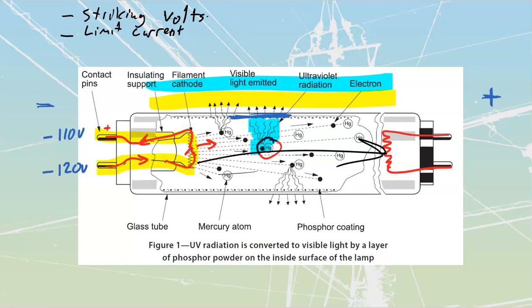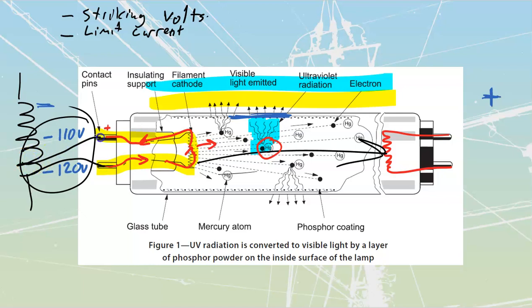And the very last thing that it is going to do is provide our cathode voltage difference. Remember how we had this over here? This is going to be a volts per turn thing. If you think back to auto transformers that we covered, remember how we talked about the volts per turn. All that there is a difference inside of our ballast. If I were to take a look at the ballast, and we haven't described ballast, and we're not going to need to in great detail, but basically this one would be coming off that turn, and this one would be coming off of that turn. And if I've got 10 volts per turn, that's where I'm going to have that difference across there. So the third thing that a ballast does is it provides cathode voltage.